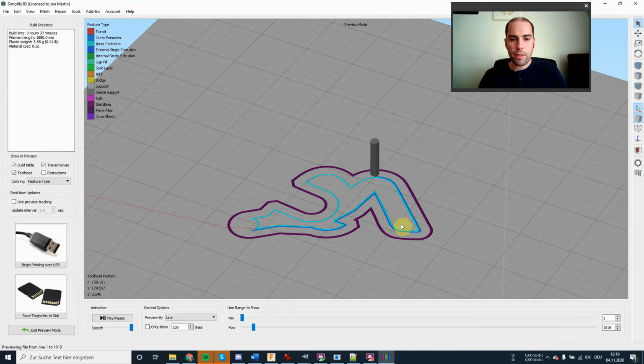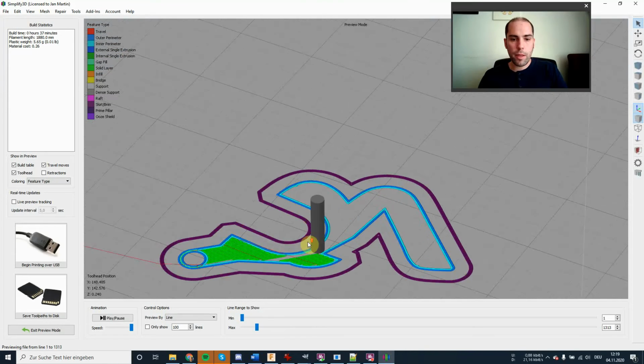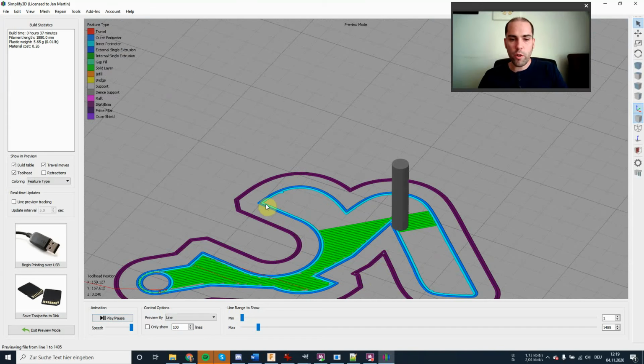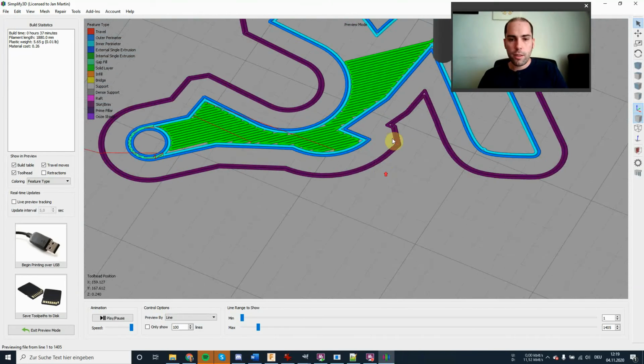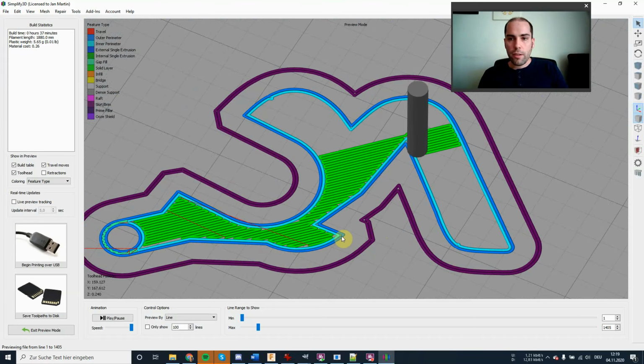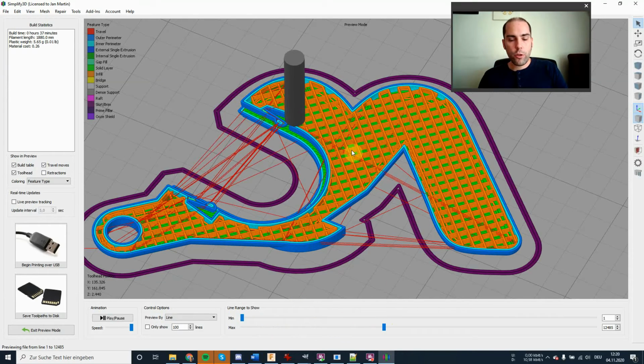What's going to happen here is that a nozzle is going to squirt the hot plastic onto the print surface. First, it's going to create 2 outer perimeters and then fill the interior with infill. Now this is external infill, solid infill, which is used to create the outside of the object. And as we are going to get inside, there's going to be interior infill. Most of the part is going to be hollow, but there are going to be these struts connecting the perimeters, so we can have more stability.